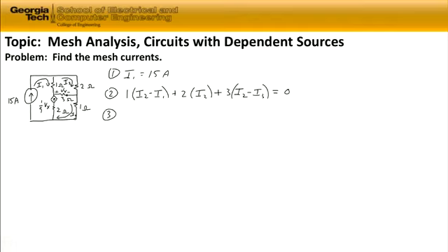We could find the voltage drop for the 3 ohm resistor as we did in the last equation, and for the 1 ohm resistor as well. But we have a problem in that we have this current source in this loop. So we really can't write an equation that sums these voltages up unless we want to introduce another unknown variable, the voltage drop across this dependent source.